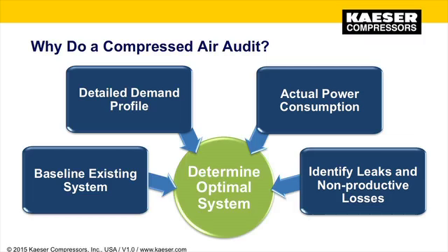Knowing how much energy you use to compress air should be a primary goal. An audit will help you do this and help you identify components of that cost, such as leaks and unproductive uses. The data collected can be used to determine the optimal mix of compressed air equipment for the existing need or future expansion. An air audit from a competent compressed air professional is a great first step in determining compressed air efficiency, along with a leak detection audit and evaluation of each compressed air user will improve overall system performance.